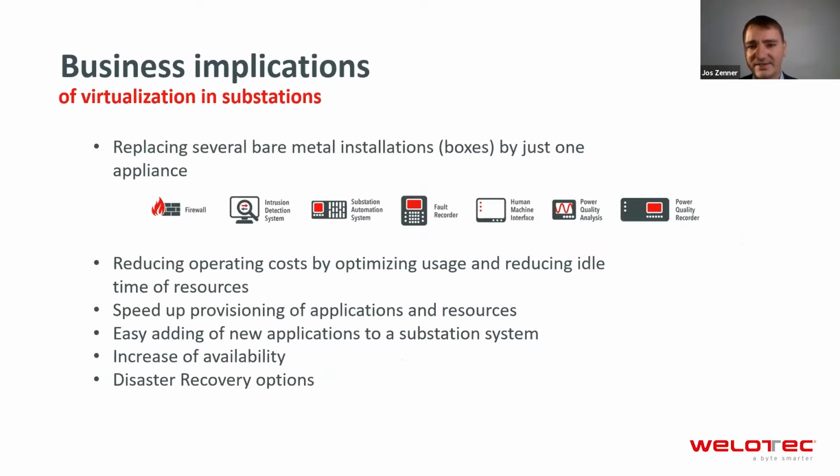So the idea about virtualization is separating the hardware and the software. And so we get some kind of software-defined substation automation and substation security system. This means that bare metal installations, boxes like firewall, intrusion detection system, any SAS system or SAS gateway, fault recorder, HMI, and power quality analysis can be virtualized on one or several redundant computer or server systems.